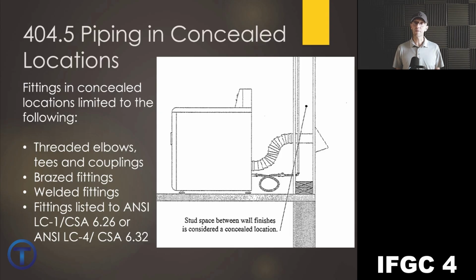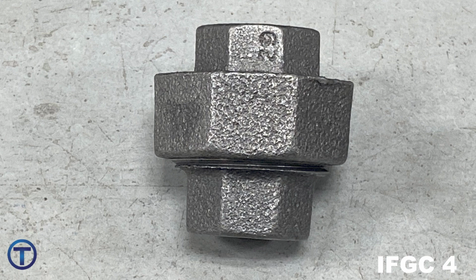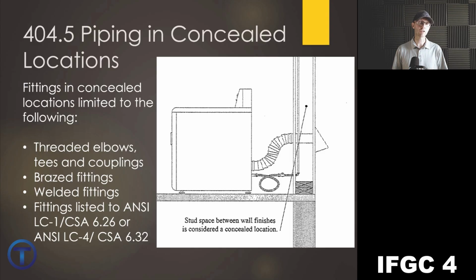May I point out that that excludes unions. You're not allowed to put unions into the pipe system where it's going to get buried, because a union is a potential leak point. It could come loose and start to leak.